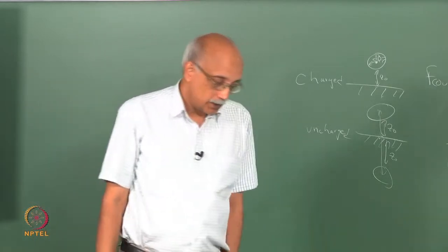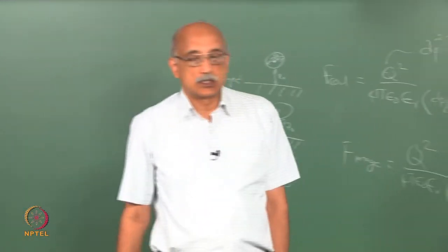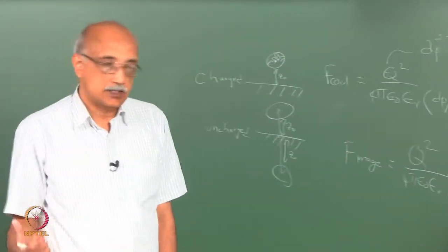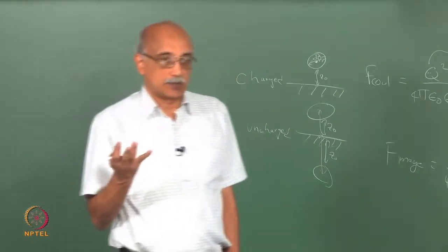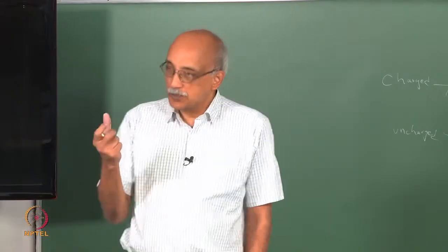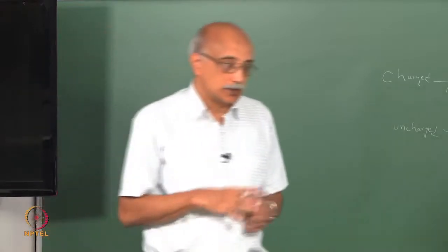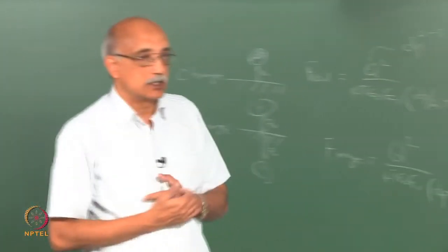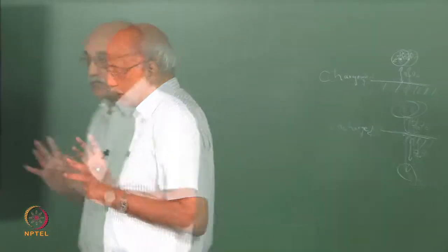So, in a medium in which you have zeta potential as a controlling mechanism, there are many ways in which you can affect the zeta potential, and typically controlling the pH is one method, because when you control the pH, you are controlling the level of dissolved ions in the liquid, and that has a significant influence on the zeta potential.